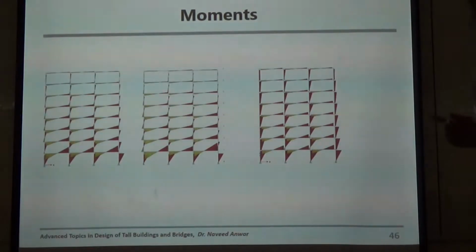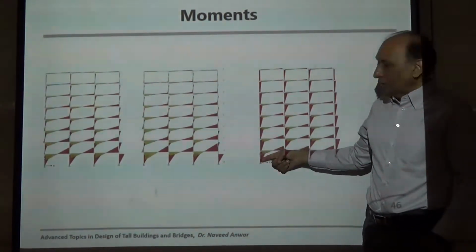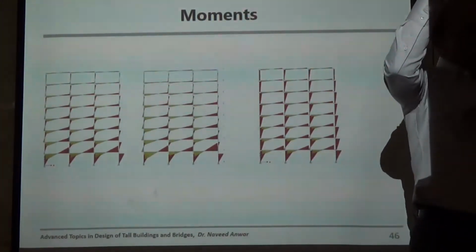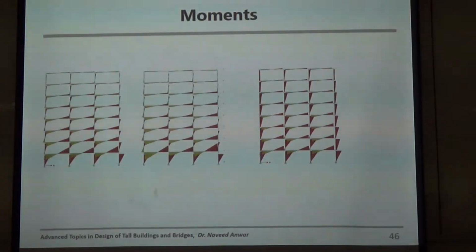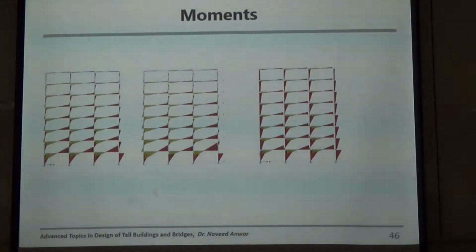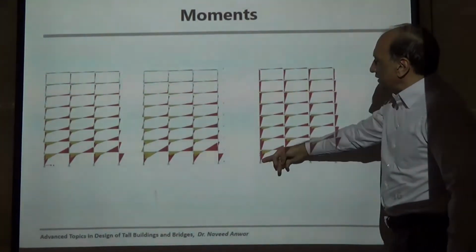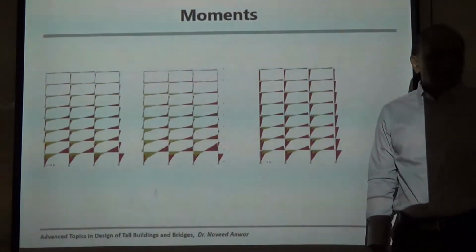This is a fact that many people may not realize, that the columns do not act from one floor to one floor. The column may be acting between several floors because the moment is not being reversed each floor. So depending upon the size, the column behavior changes, and that is the reason why this has larger deflections than others. Okay?